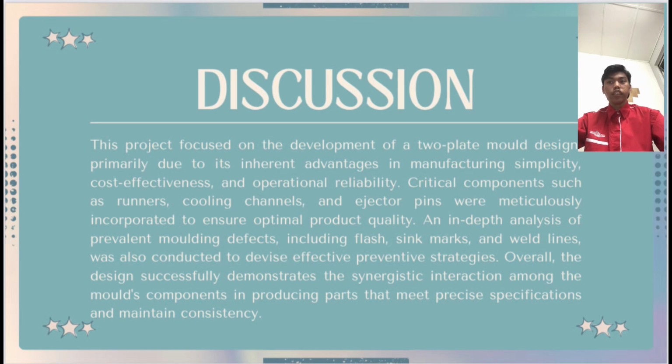The discussion is, this project focuses on the development of a two-plate mold design, primarily due to its inherent advantages in manufacturing simplicity, cost effectiveness, and operational reliability. Critical components such as runner, cooling channel, and ejector pin were meticulously incorporated to ensure optimal product quality.